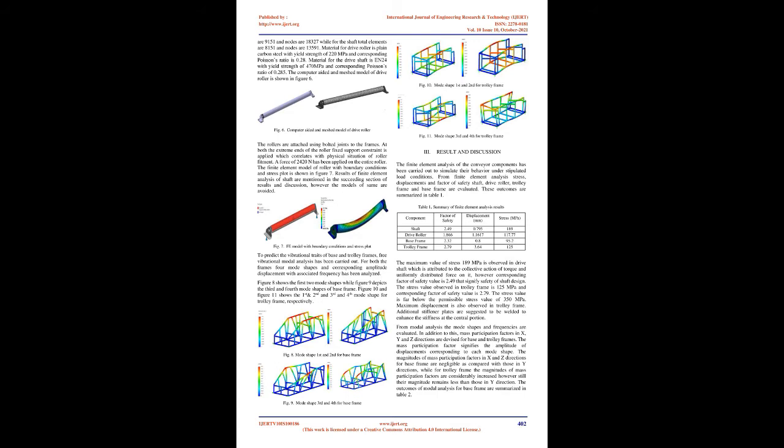On the base frame, a total downward force of 25,277 N has been applied, equally distributed over 14 different locations on top members. The CAD and meshed models of base frame are shown in Figure 2. Fig 3. Base frame model with boundary conditions and stress plot.